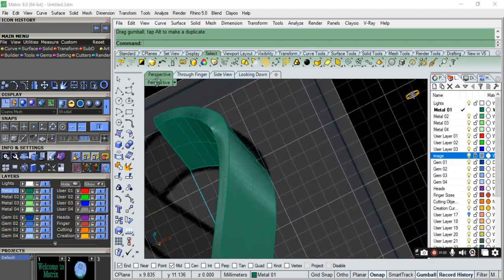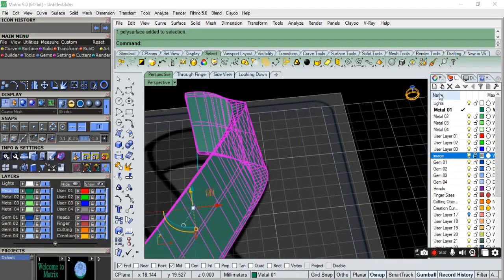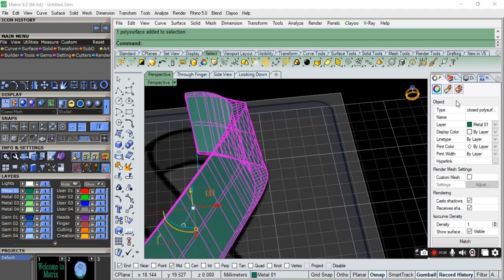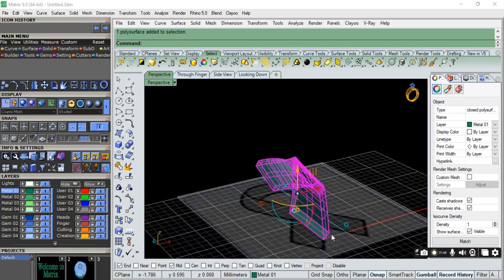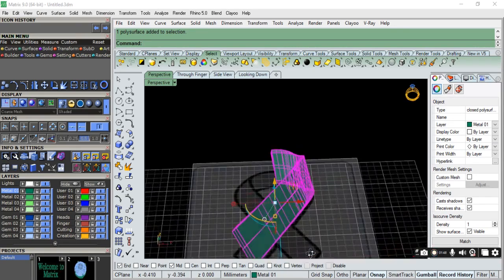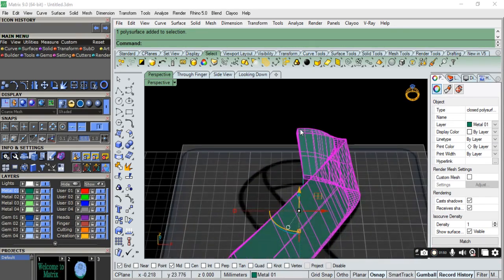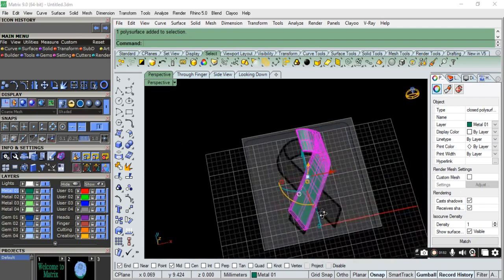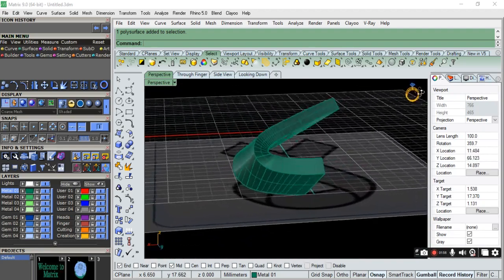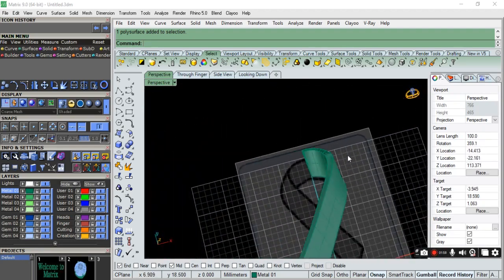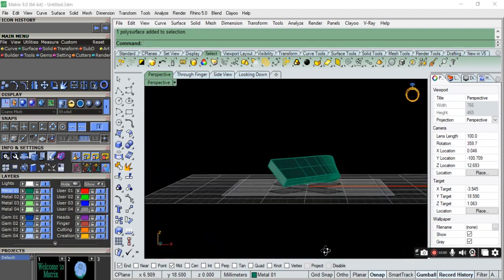See, this is a solid model, and this will create a proper solid model. But in case an error comes, you can create this curve, this curve, this curve, and this curve again, and use other tools as well. There is not only the sweep two command. There are many other tools which can help us with proper shape modeling.